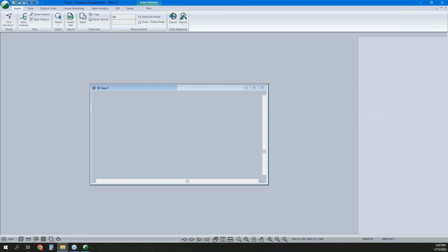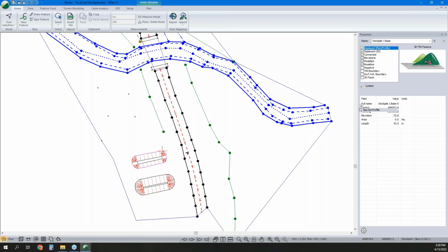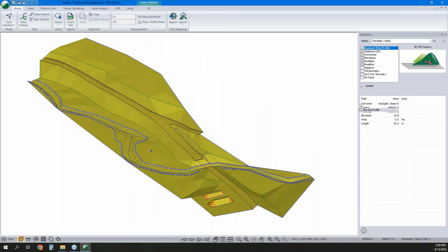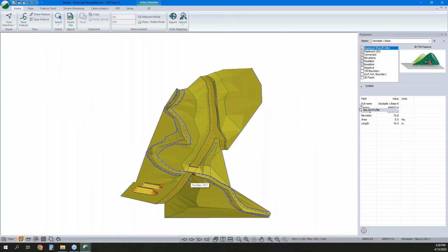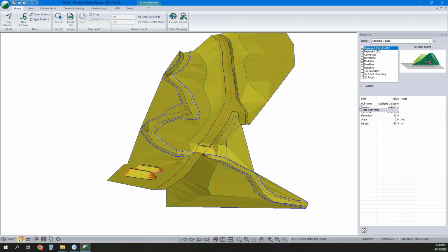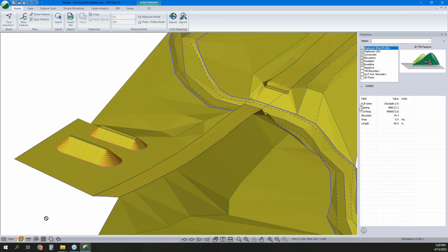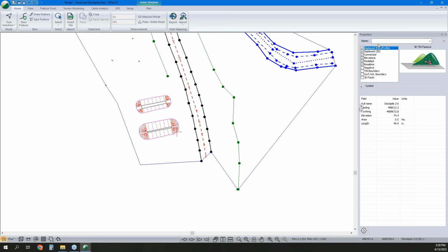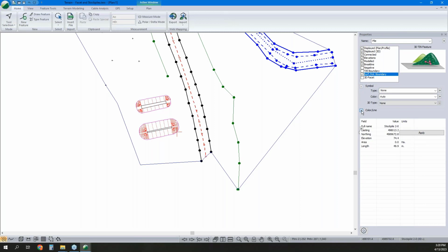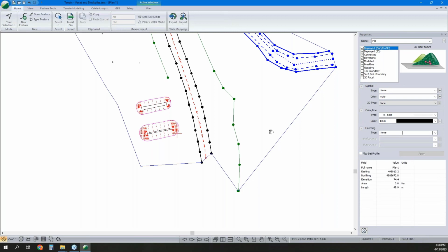So it's a lot smaller of a scale. So here I've got a standard survey. I've got these two stockpiles in the survey. I can take these features and I can say, well, these selected features, I'm going to call them pile, and I'm going to make them a surface volume boundary.